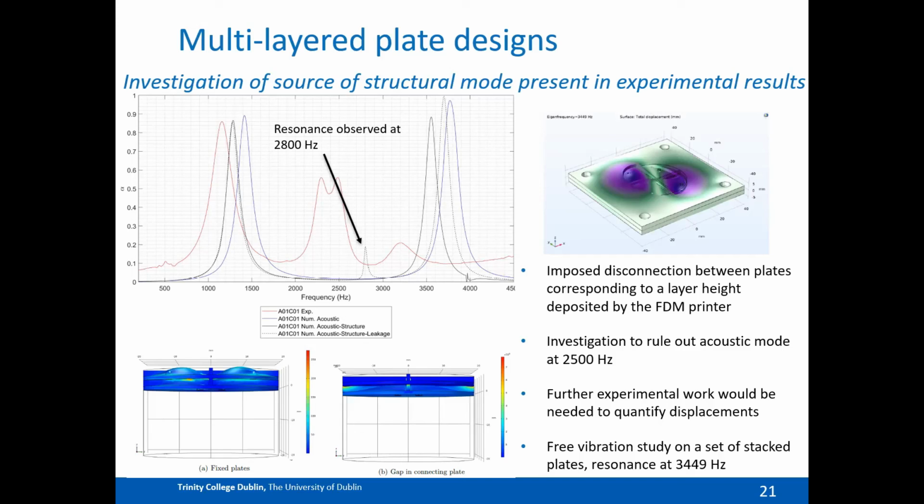And then from this, just using free vibration studies to see that the resonance shown was at around 3,500 hertz, which is quite high, but it's difficult to correct without applying proper boundary conditions, and more experiments are needed, either using a vibrometer to exactly account for this.